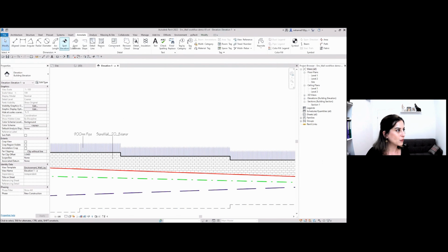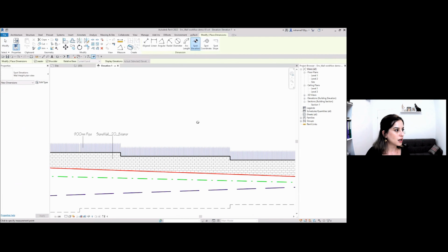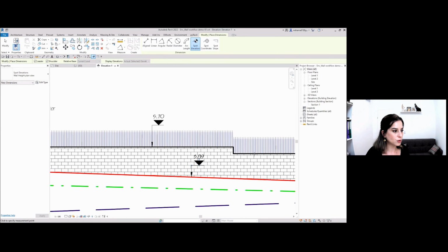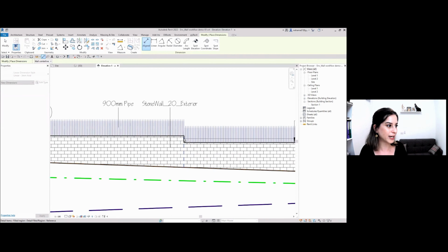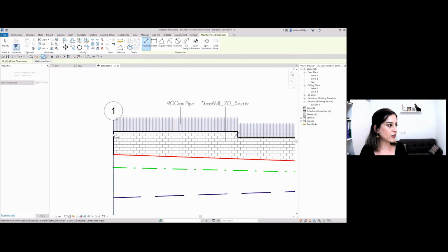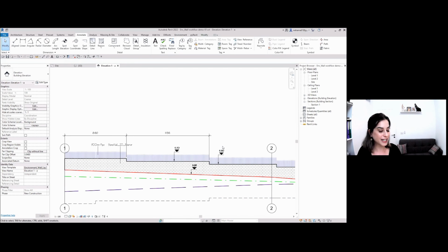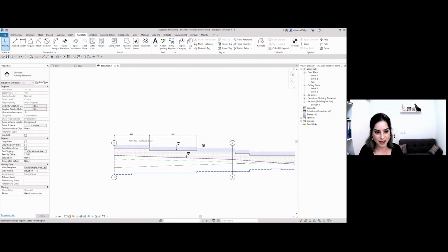Another really nice thing in this view is that it's set in such a way that allows you to actually show the real elevations of your project. So even though it's a 2D view, every elevation over here is correct, and everything, of course, is according to your project units. So if you work in imperial and I work in meters, that's okay. You can work in imperial, it will be okay. Just like Revit, it inherits your project units. So there we have it, a complete wall workflow in just a few seconds.